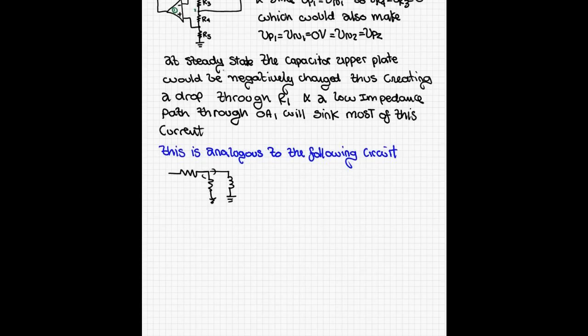So let's redraw this really quick, just to conclude. So then again, IL is max, and VL is equal to 0 volts. So thus we explain how the circuit actually works, just doing a simple experiment of AC analysis, DC analysis, and we figured out that the circuit actually behaves as a grounded inductor.